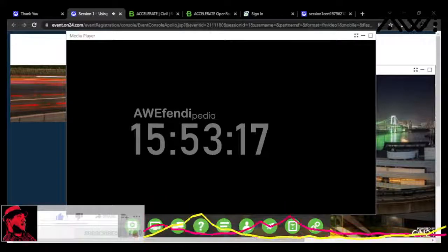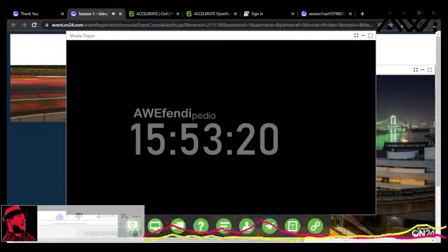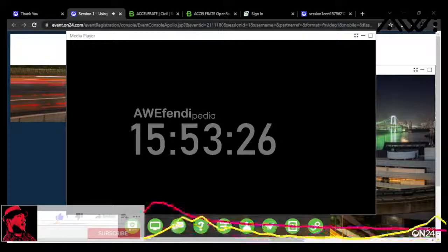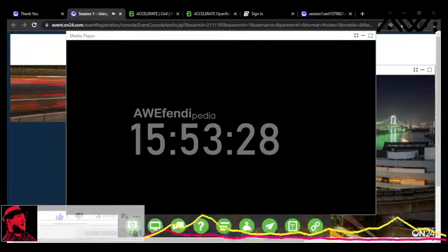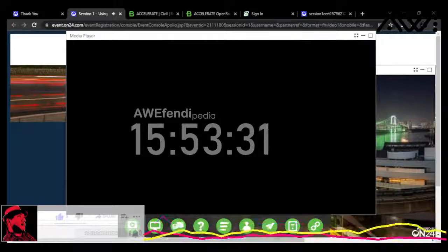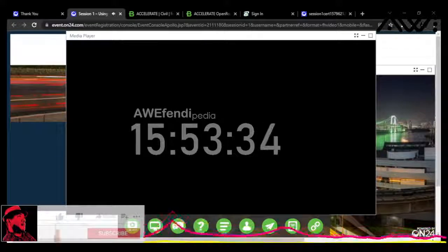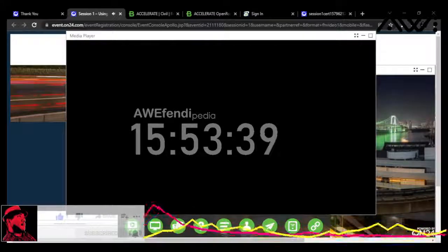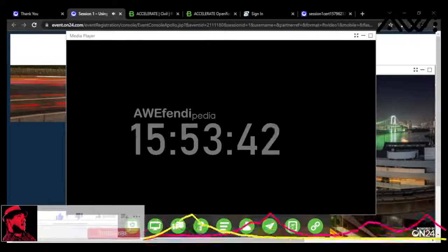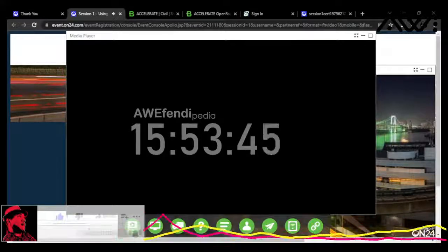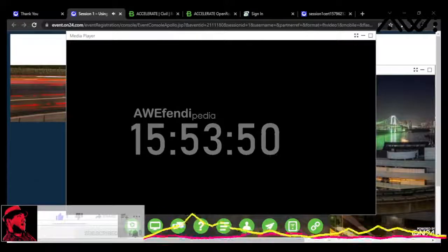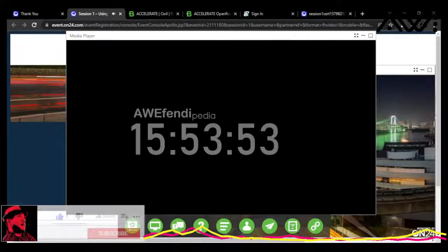Next, I do want to take some time now to look at the settings that are set up in our workspace or in our seed files. Because really the power of this survey program is, if I have all my settings and standards set up and I've trained my field crews how to code the survey data coming in, I can almost do 2 or 3 button pushes in order to import data and then get out a good terrain file. So I'm going to spend a little bit of time on that here at the beginning because it is so important with the survey product.